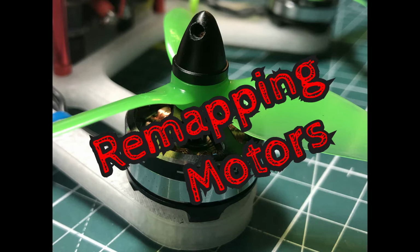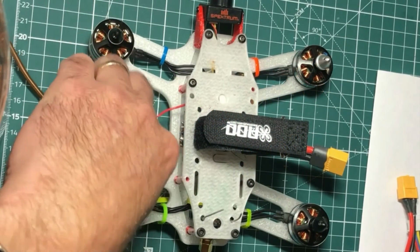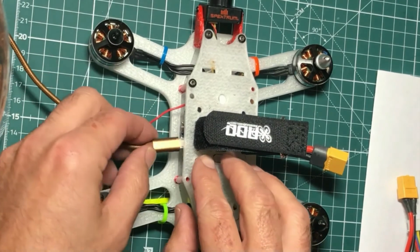If you have motors that aren't spinning in their proper position, for example, motor 1 is actually spinning motor 3, etc. In Betaflight, you can remap the motor resources. So I've got a quad that is actually mapped incorrectly, where motor 1 is spinning motor 3 and motor 2 is spinning motor 4, vice versa.